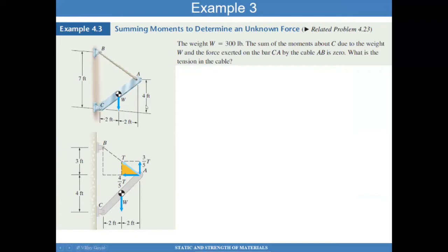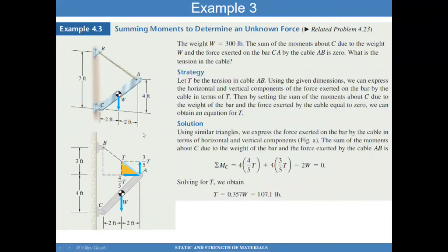The first step is to determine the tension force acting on this cable. So I can cut it right there to figure out what that is. I know the slope of this cable, so I can calculate that this y component is 3/5 times tension force T, and this component right here is 4/5 tension T. So I was able to decompose these tension forces.